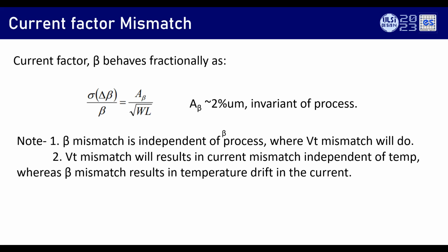For example, in the band gap, where you don't care about the absolute voltage but you care about the tempco, you really don't care about the VT mismatch. You care about the beta mismatch more than the VT mismatch. So this is the takeaway I want to show with the slide. Sorry, something messed up with that formatting. But how do we predict VT mismatch? We need to foresee how process variations will show up, again through simulations. It's Monte Carlo.